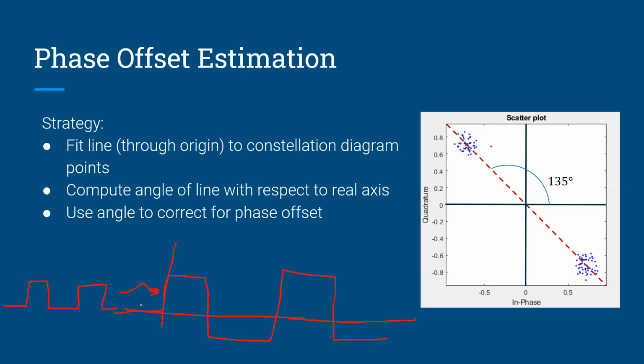When these two line up, you'll get a spike in your cross correlation, and that spike denotes where your packet starts. And if you don't know, cross correlation is very similar to a convolution, minus the flipping.